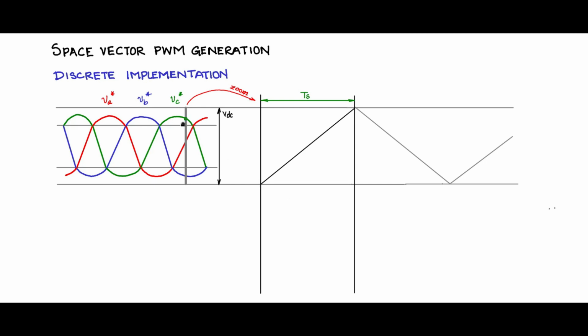Now we will mark the intersection points. The VC, which is at the maximum now, has an intersection point there. There is an intersection point here for the VA waveform, and there is an intersection point here for the VB waveform. So let us extend that so that it cuts this voltage-to-time conversion ramp like that. This height is VA height, I will say. This height will be VB height, and this height up to this would be VC.